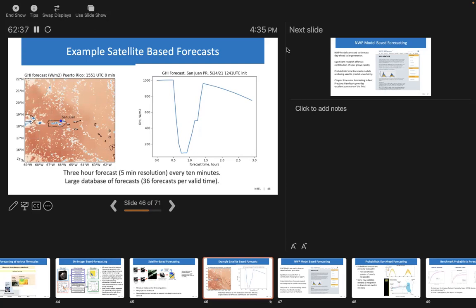What this variability is, mostly when you don't have batteries and your whole region has generation that is fluctuating, is that during peak hours you have to pull up some of your reserve to essentially balance the grid. So that's when this comes into effect.